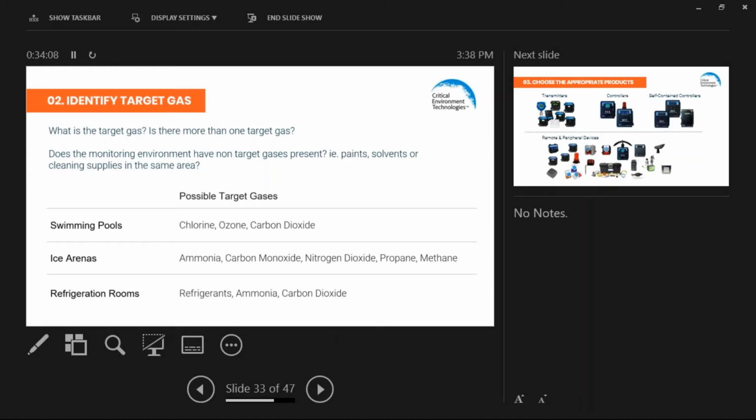So what they're doing is they're taking high levels of carbon dioxide, and as the water goes through the chlorinator to be cleaned, they're then feeding in high levels of carbon dioxide to help maintain the pH level of the water and thus cut down on the chloramines.